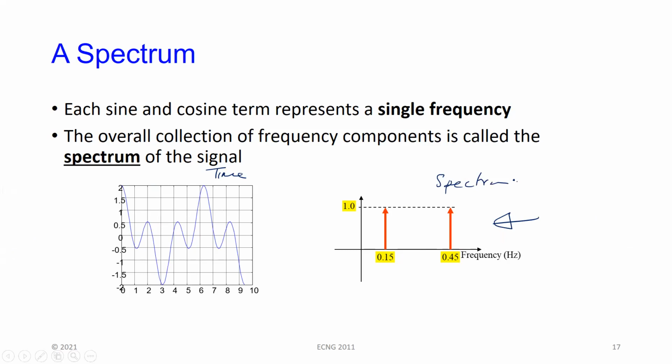Notice both of them are giving you the same information, just looking at it from a different point of view. And in fact, in one case, you get more information than the other. This one is telling you something about how the signal amplitude is fluctuating. There's a peak to peak of almost 4 volts here. And in between, there's another peak to peak here of about 1 volt and so on. So you're getting some idea about it, and you could look for inconsistencies.